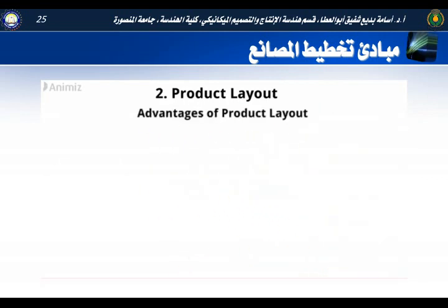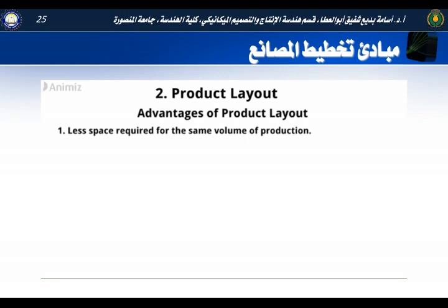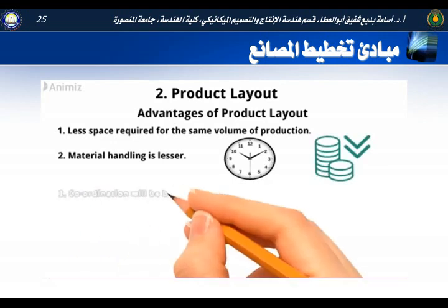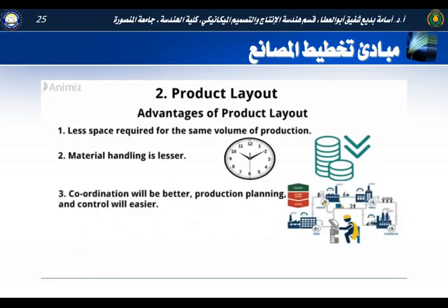Advantages of product layout. 1. Less space required for the same volume of production. 2. Material handling is lesser, which reduces time and cost. 3. Coordination will be better, production planning and control will be easier. 4. Fewer skilled workers may do the work.